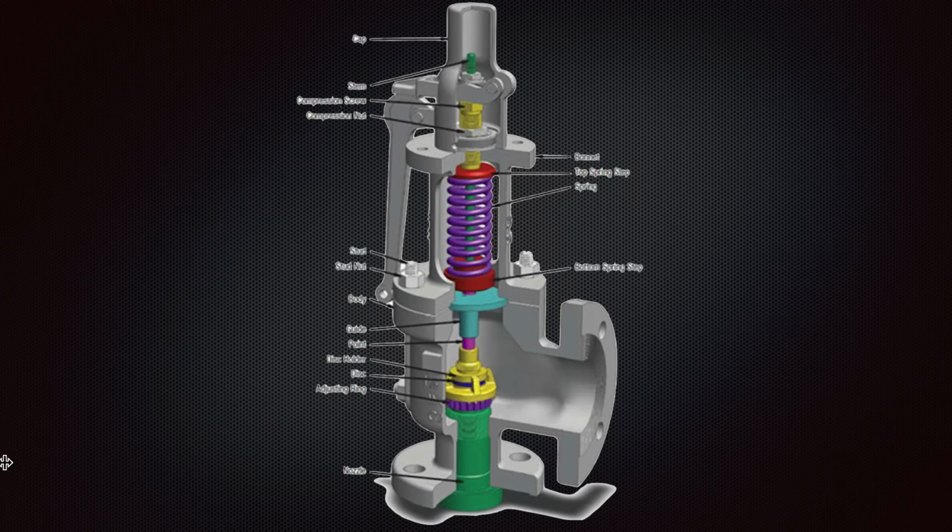You do not want your safety valve to open lower than the normal setting, because you will lose steam and you will also get some disturbance to the operation. Just imagine if you operate your boiler at 15 bar and it opens at 14 bar, you will get some steam out, and then you need to identify if there is any alarm ongoing, whether it's real, and from where it is. You need to adjust the system again and put it back to the normal range.